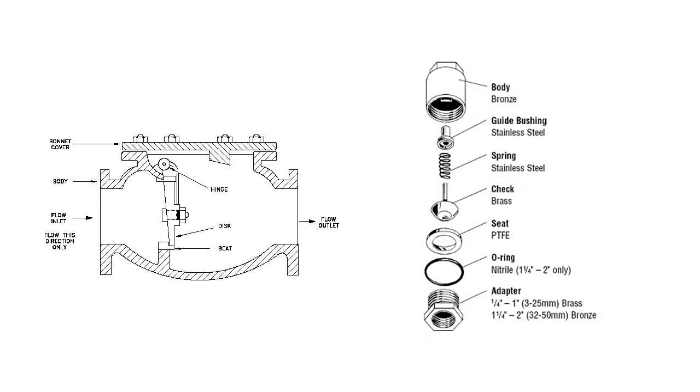This valve can be installed in any position because the spring will force the valve closed whenever the flow of fluid stops. These check valves can be installed in any position, which is a really good advantage, but have a higher pressure drop than a swing check.